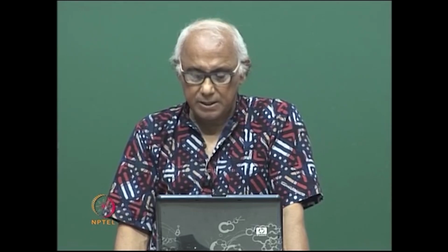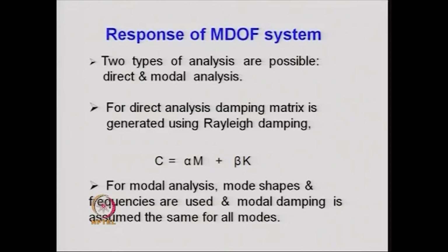In the single point excitation, we have an influence vector or influence matrix that generally consists of 1, 0, 1, 0 etc. For multi support excitation, the I is replaced by R. R is a matrix called the influence coefficient matrix, and that is generally obtained by performing a separate static analysis for the differential support movement at the base, and how we obtain the value of R, that we have explained with the help of a few examples also.